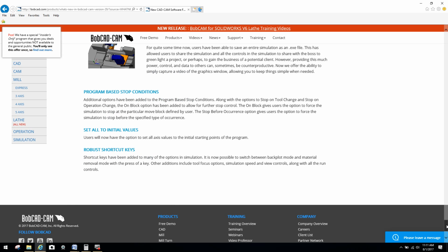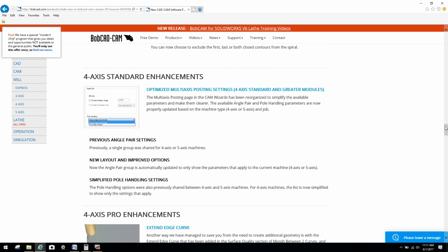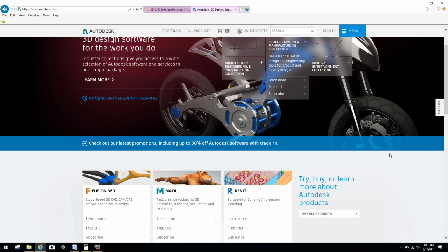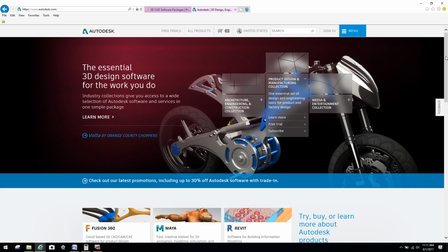The price behind these softwares, I can tell you right now, will range in the thousands, guys. So when you're looking at your hardware and at a fifth axis machine, the Chinese are now selling fifth axis micro mills for probably a little over 2,000. You're doing a retrofit, 86 those Chinese drives. Get yourself some quality drives, preferably Geckos. We do a full articulation retrofit. You're looking at a minimum of another 1,000 to 1,500 just to do the retrofit on the controller, and then figure in this software, and then you start really seeing the true investment of what you have.